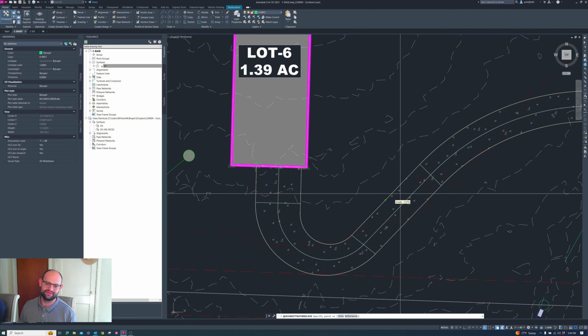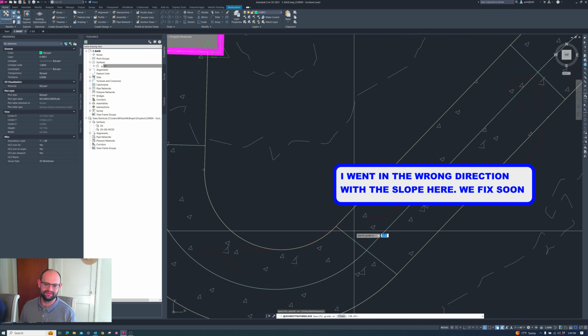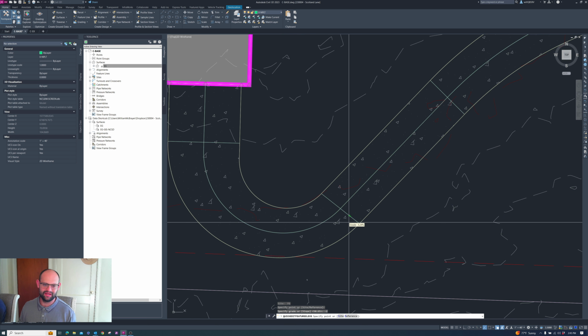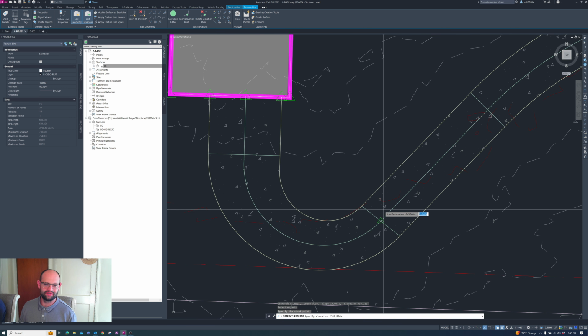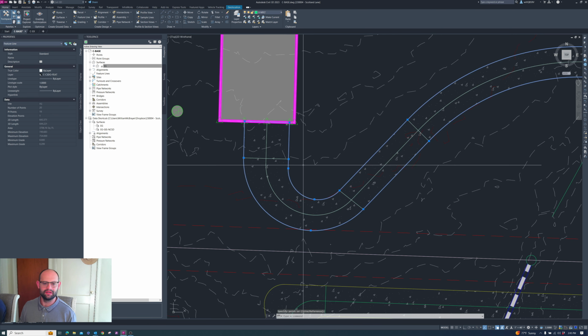That part of the crown's already set, so let's go back here. 2% down, away from the center. We have another vertex here, so let's keep this side smooth like the other one. Click. Same thing for the center line. Okay.